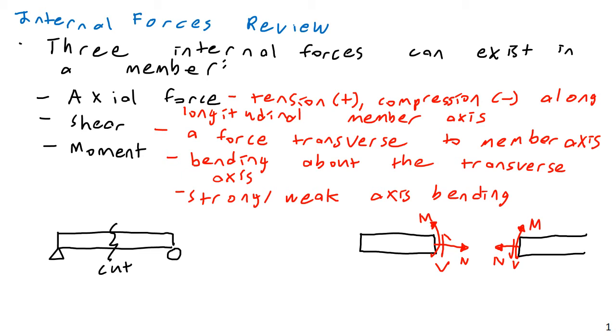Yes, very good. Opposite directions, matching pairs. Basically, this is just Newton's laws. For every action, there's an equal and opposite reaction. When we look at internal forces in a beam, in a column, things like that, wherever you have a cut, there is going to be an equal and opposite force.